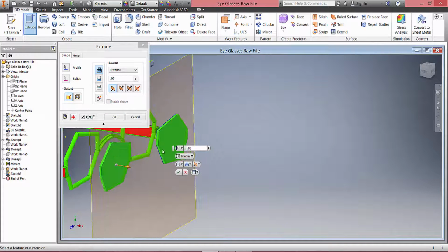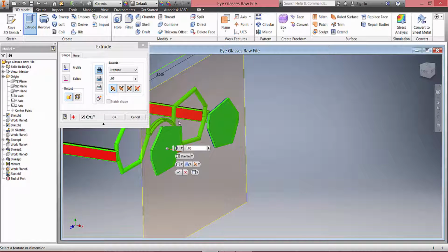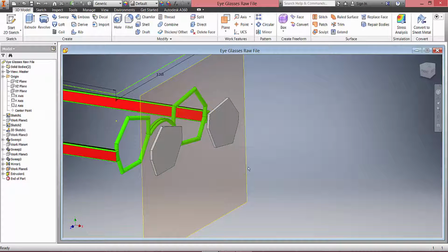And also, this is the most important part. You want to make sure that you are not on the extrude option, that we're actually creating a brand new solid, because we're going to make the solid of glass. We cannot turn the whole thing glass. We just want this portion to be glass. So I'm going to go to a new solid, click on that, and then press OK. So my glasses are made, and now we're going to turn these to glass.